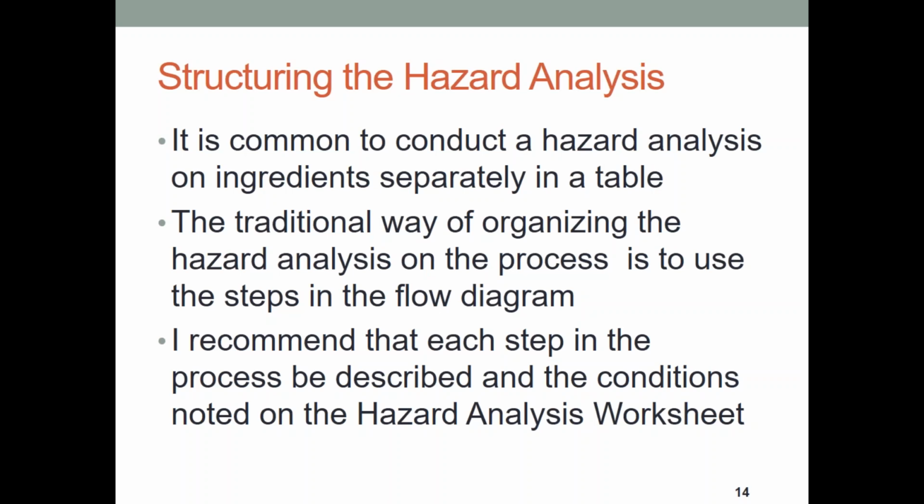Okay, but the traditional way of organizing the hazard analysis on the hazard analysis worksheet is to list the steps in the flow diagram. That verified flow diagram, list the steps there. And normally when I teach hazard analysis, I recommend that each step in the process be described and the conditions associated be noted on the hazard analysis worksheet. I'll show you a hazard analysis worksheet at the end of this presentation. But essentially what I like to do is to the left of each step in the process, I like to describe what's happening at that step so that someone who has taken a look at the hazard analysis worksheet understands just what we're dealing with.